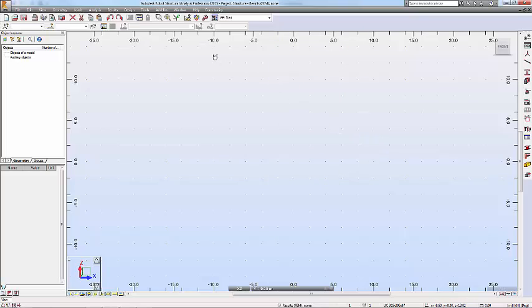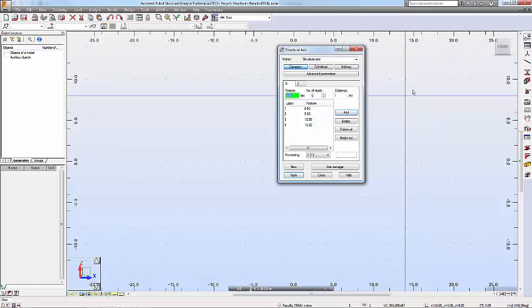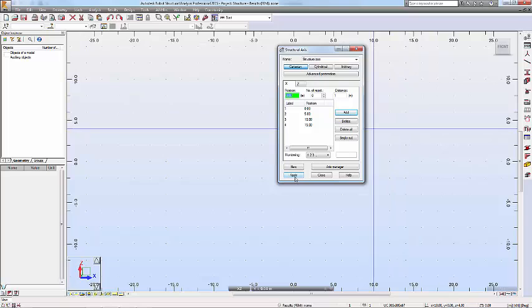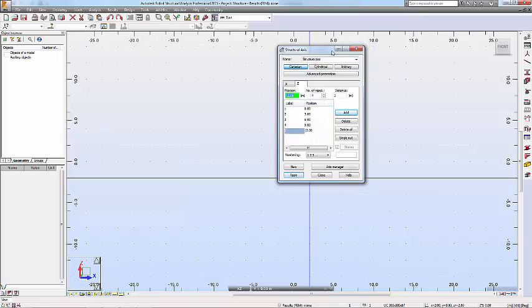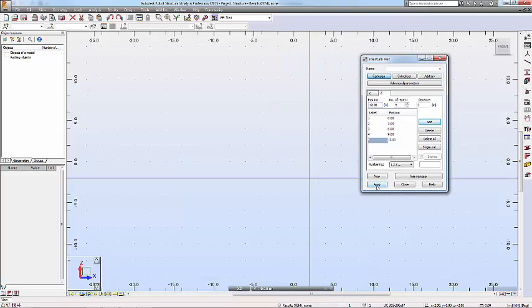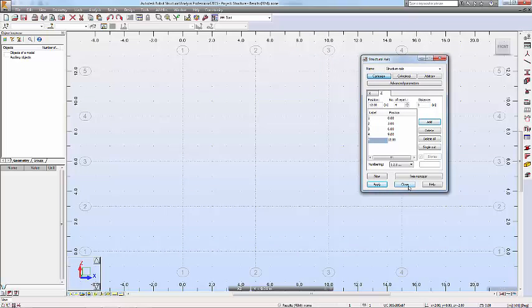here, but maybe it's not easy to see. Let's click on zoom. Sorry, maybe it hasn't been created. Sorry, I forgot to click on add. So the Z direction actually hasn't created any story yet, so we need to do it again. So 4 and 3, and we click on add. So this one is added into the system, and we click on apply. Then this column line system, this axis, has been created.